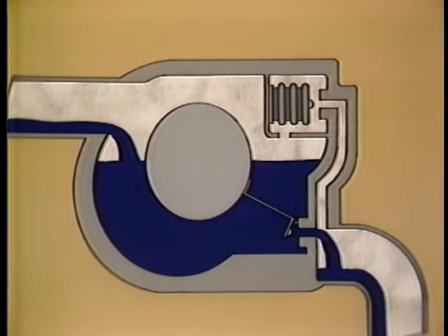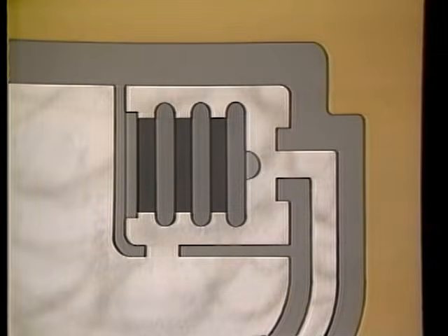The condensate drains from the trap through the outlet near the bottom, leaving a condensate seal between the inlet and the valve. Above this seal, near the top of the trap, is a thermostatic bellows. The bellows responds to temperature change. When this space is filled with hot steam, the thermostatic valve is closed.